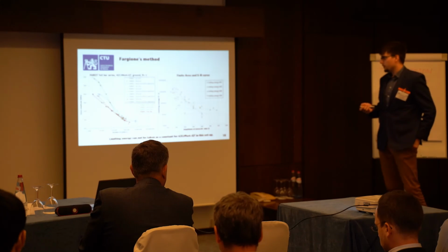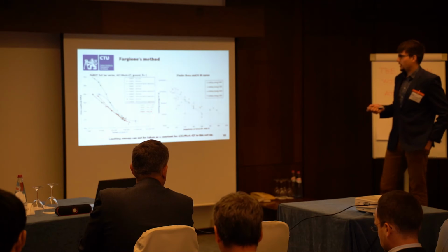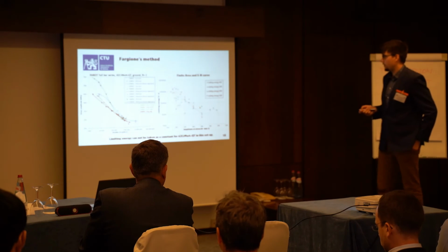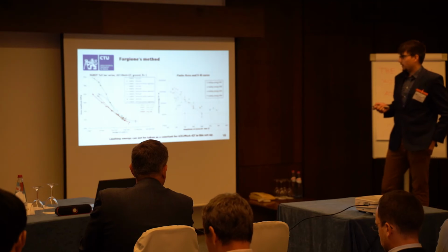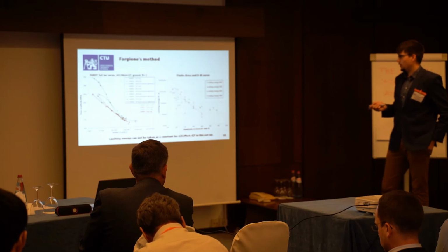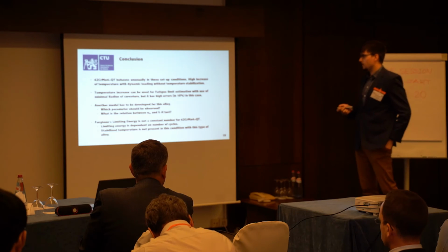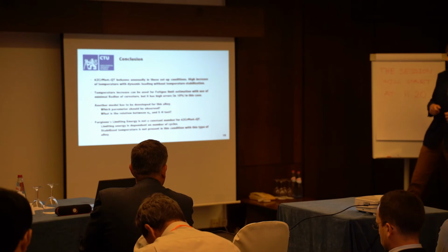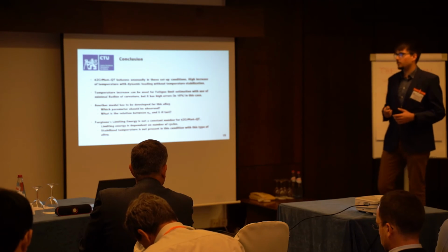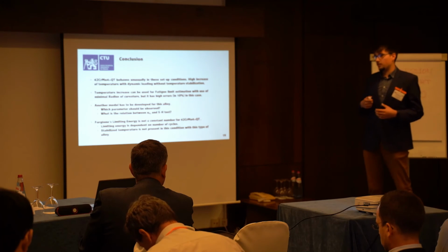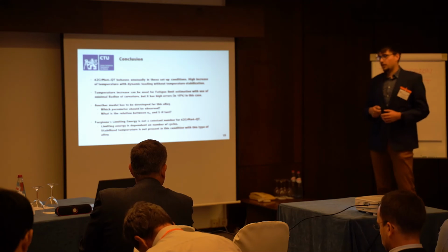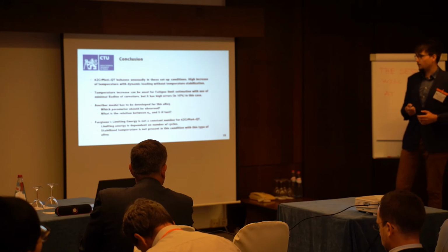And as you can see here, on the right side, the limiting energy, which is the area under the temperature evolution, is highly dependent on the amplitude of load during the fatigue life testing. So I come to the conclusion that the material that we use behaves quite unusually in this condition. This is mainly due to the fact that we are not able to change the frequency of loading. We are planning to do this test on a hydraulic machine where we can adjust the loading frequency.